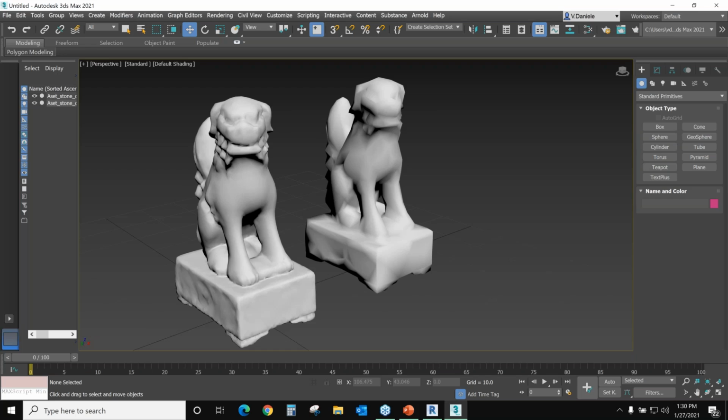If yes, then we probably want to have a more detailed mesh. So we want to keep that to a higher poly level. If it's something that's kind of off in the distance and we're not going to be right on top of it, either in a rendering, a video, animation, or walkthrough, then we can get away with it being less detailed, which ultimately overall is going to affect the performance of your immersive experience if you're using VR or something else.